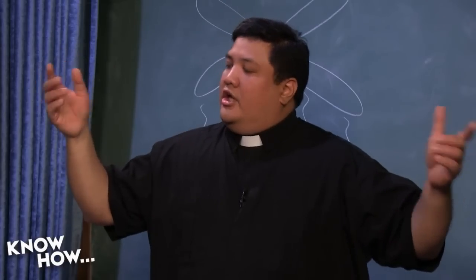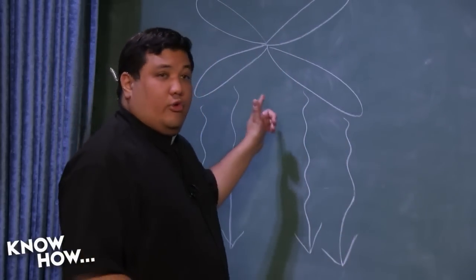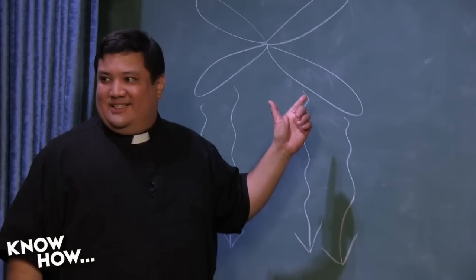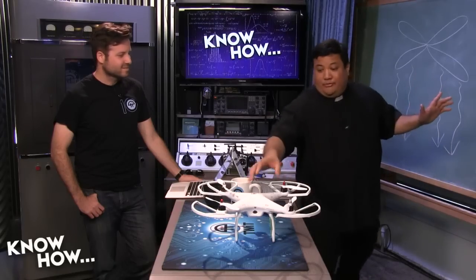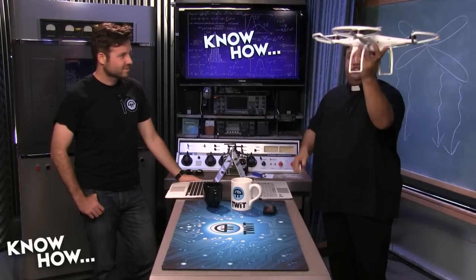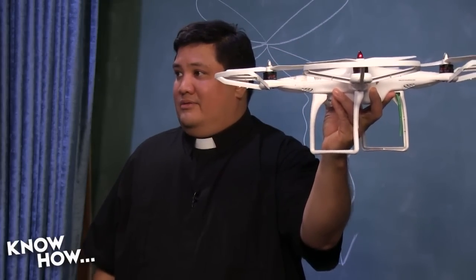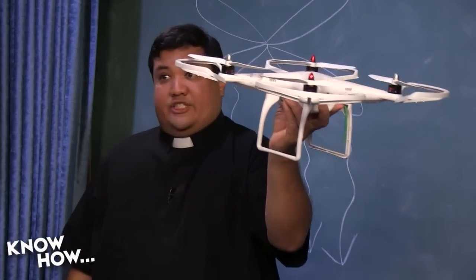Now, a lot of people will panic and goose the throttle, because you think, well, if I'm losing lift, add more thrust. The problem is, if you're in a vortex ring state and you add thrust, you just make it worse. So what do you do to get out of it? It's very simple. If you're descending and you're in a vortex ring state, move it a tiny bit forward until you get to a clean space. And that's what helicopter pilots have been trained to do.